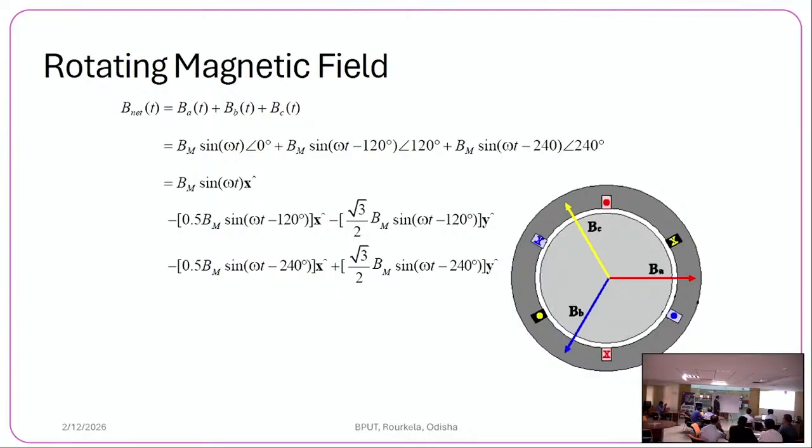Alright. So if we draw the MMFs at time t1, this is F for phase R. MMF for phase R is the maximum. This is along the same axis. Along the Y axis, this MMF is FY, and this is FB. I have shown one longer line. This is half of that, because the MMF is proportional to instantaneous current, and the phase is the space position.